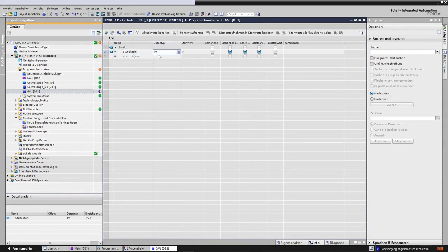Then I have my quantity with the initial value of 0, and it is dependent on the name. There is no fixed address. The same applies to a Boolean variable, for example, SR block. I can call it SR01 and declare it as a Boolean value. It only exists once. I can set it twice, but there is no overlap, no double allocation, as I just showed.